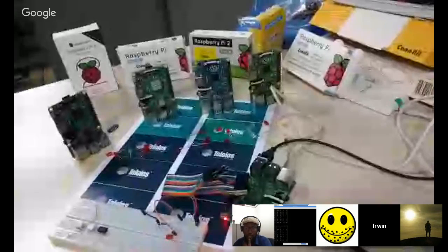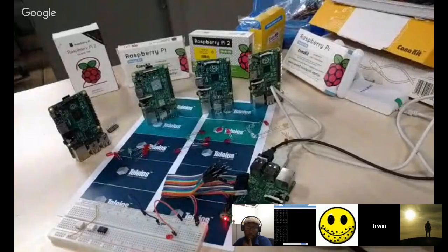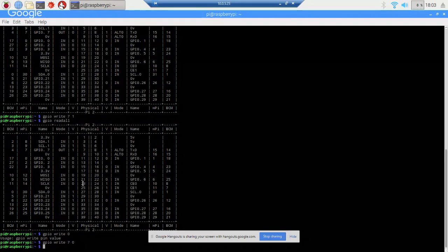Nice. What I like from this is you may actually want to test a set of interactions with a sensor, or not just an LED, something else on the board. You want to make sure you are talking to the right pins. I love that you can just come to the command line and run some quick tests rather than writing a bunch of code to compile and make sure the thing actually works. Yeah, definitely. Without this, you would have to dig up a lot more stuff. Plus, you see that even the most basic, simplest things could just not work when you need it the most. And something as simple as a reboot could just help your life.